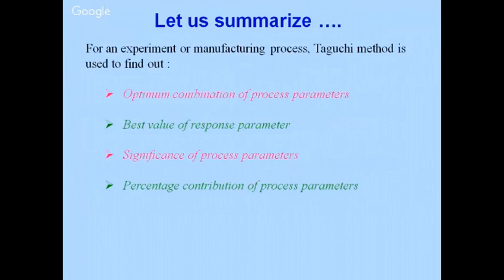This is very relevant when we go in for higher arrays, like L18 or L27 arrays, because we are conducting only a fraction of the experiments, but it is still able to tell me the optimum combination and how much response characteristic value you will get if you conduct the experiment on these values.